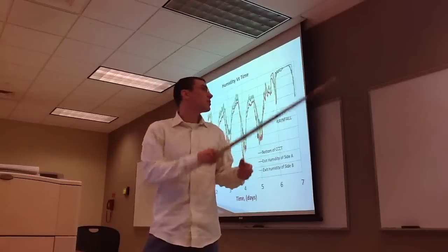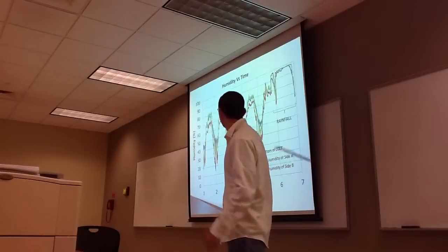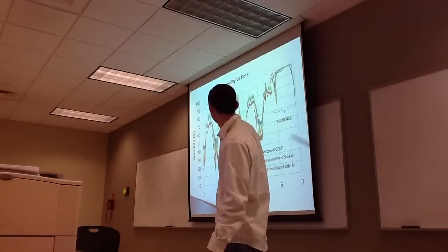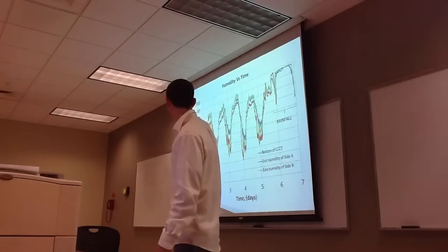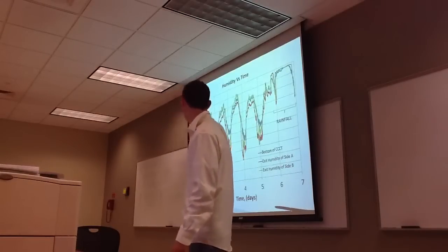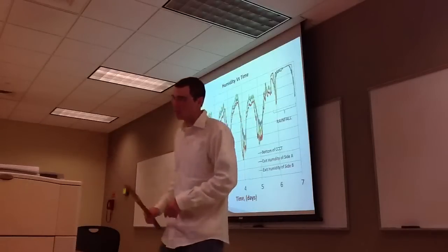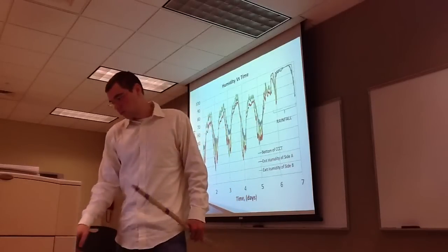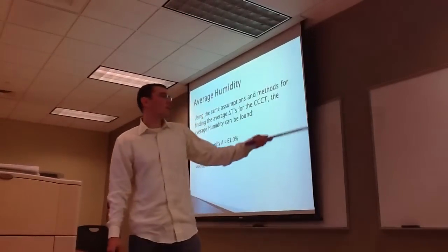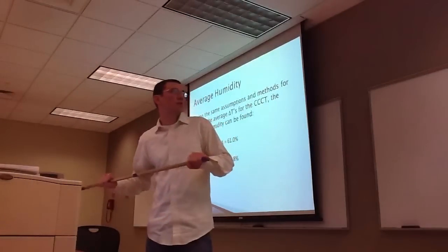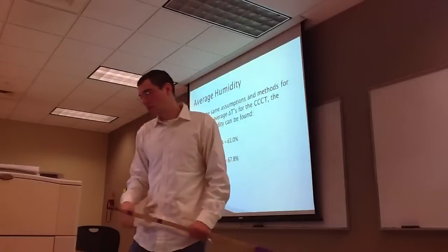These are the humidities, because that might have had some effect on the heat transfer rate. You can see that during the night it goes up, and during the day it's lower. This was taken in the afternoon at time 1 all the way to 7, which was when it was raining again, where the humidity went to 100. Since humidity is relatively similar, I calculated those out to be about 61% over the course of the entire week period, and 67%.